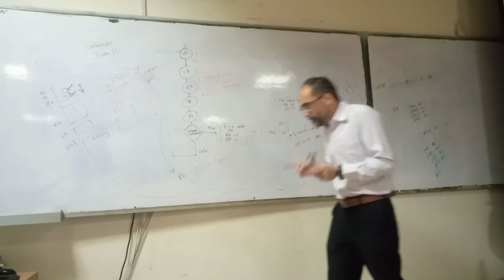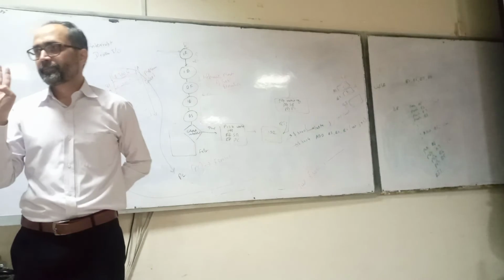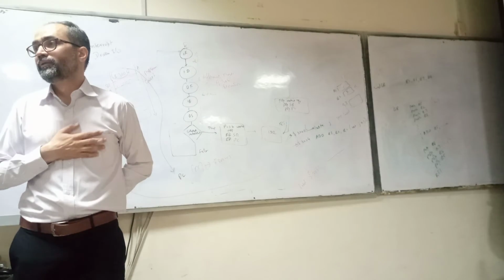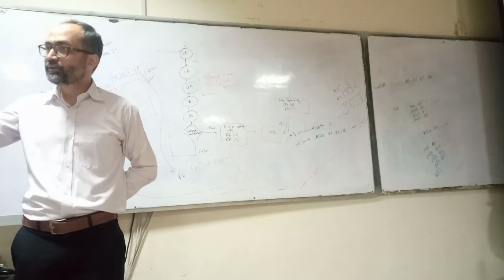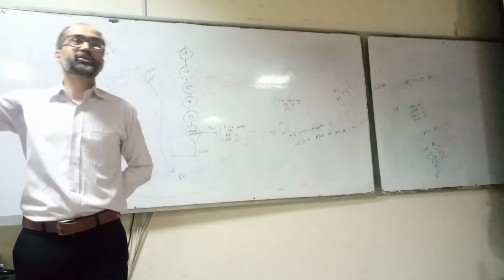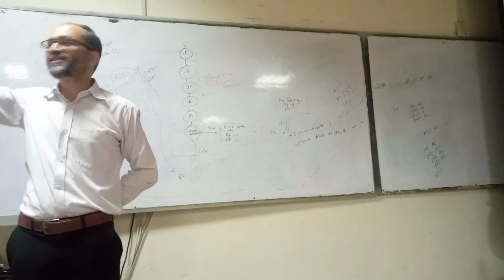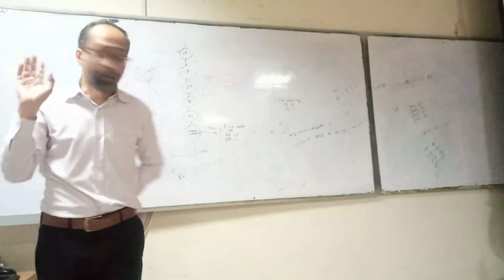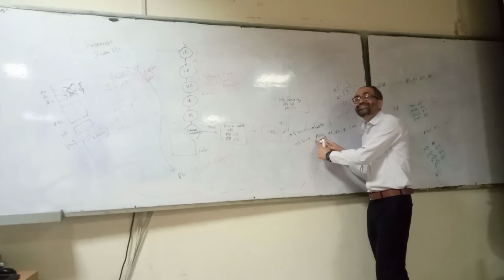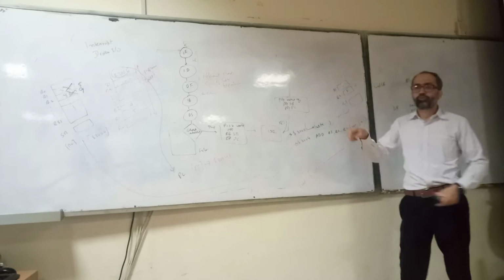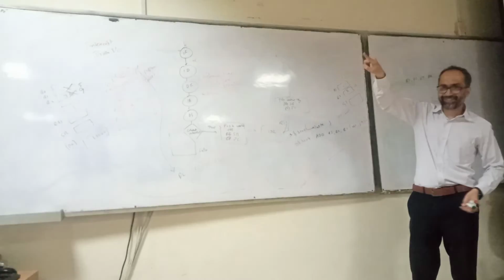Okay, and if you remember, we studied in our first lecture that there are three types of instructions. Number one, what kind of instruction? So instructions for a microprocessor are broadly categorized into three types: data transfer instruction, data transformation instruction, and then control instruction. So any instruction can be categorized into these three types. Now, what is the instruction add? Data transformation instruction. If we say move, it is a data transfer instruction. If we say jump, it is a control instruction.